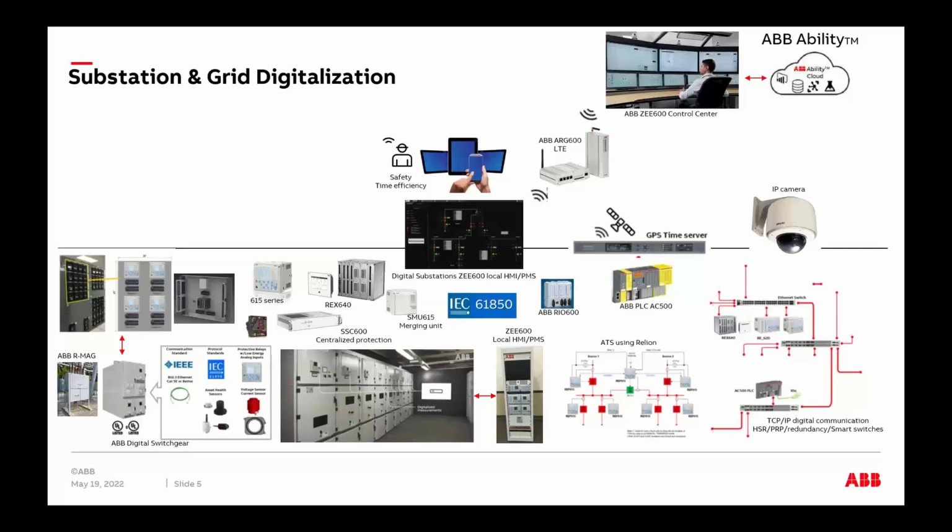And also at the same time, when you're doing this, you're thinking about what is required today and how you're going to fill up the whole project in 2 years, 3 years, 5 years, whatever the window will be. Because you could be starting with a small substation. Maybe in 2 years, that substation will become a huge substation. Maybe that's substation number one. You're going to add another substation number two. So you've got to think about how the two are going to work together in parallel and have all that communicated to one site where you could monitor both substations.